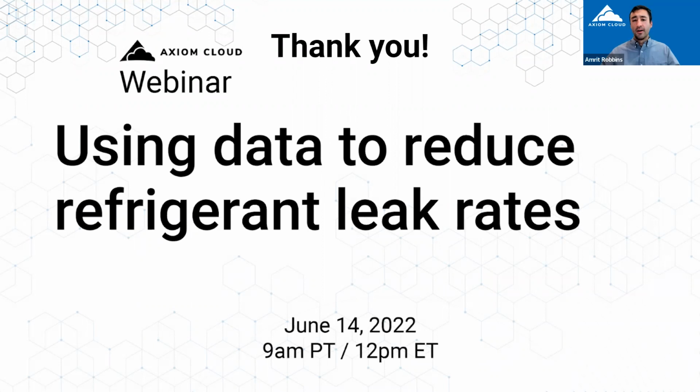Yep. It's so interesting to hear the sensors you guys are saying. It exactly aligns with my thoughts here. Basically, receiver level, analog's better, digital is not as good. Outdoor air temperature, the really cool thing there is that you don't actually need that sensor on site. You can get that from hyperlocal weather services really easily, and it's good enough typically. And in many cases, the outdoor temperature sensors on roofs we found are super unreliable because they get hit by the sun or they're under the condenser, and depending on the condenser mode, et cetera, they're providing weird data.